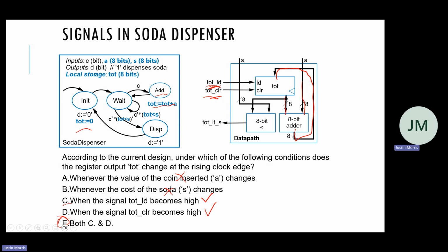Yeah. So even if you are at an initial state of total is 0, when the total load signal is high, then that pushes that 0 to activate the 0 plus A adder. No, it would just be inside this register. It's a register that has this control of clear. So like in your lab, you made a synchronous reset register and an asynchronous reset register. The clear is the reset. So it's an input into the register. It doesn't care what is on the input here.